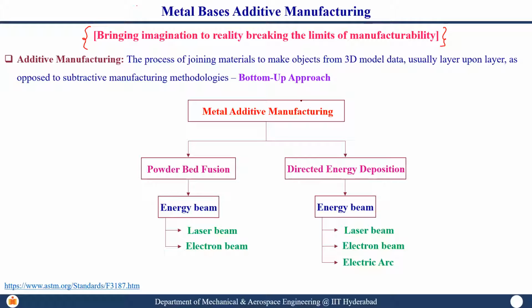Even if you talk about the powder bed fusion process, people think it is very easy to deposit a component on it. But we need to understand that the powder bed fusion system that comes with the license for a particular material has process parameters already set into it, which each company has worked on for more than 5 to 10 years to optimize for that particular material. So that's why that license becomes so costly.